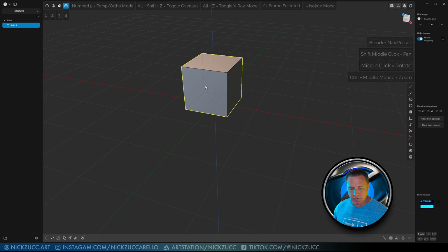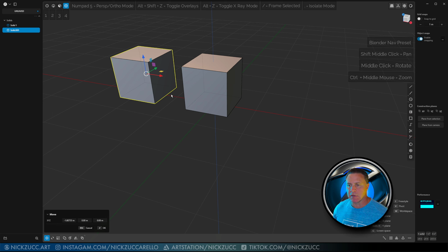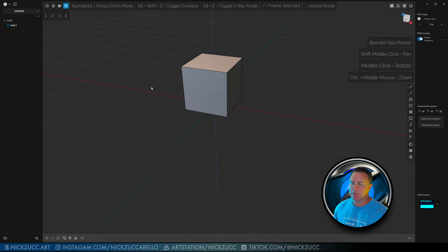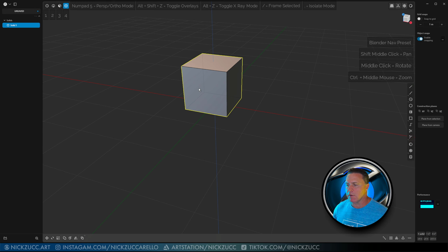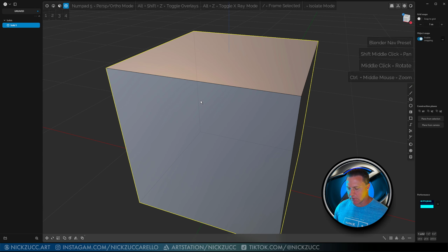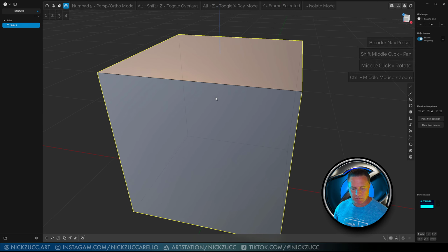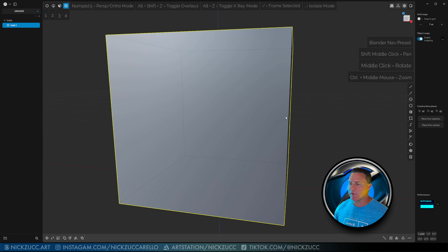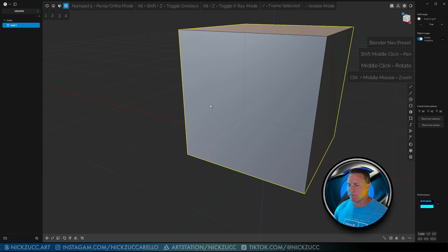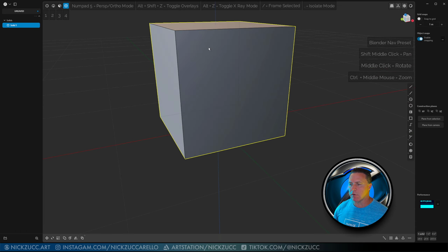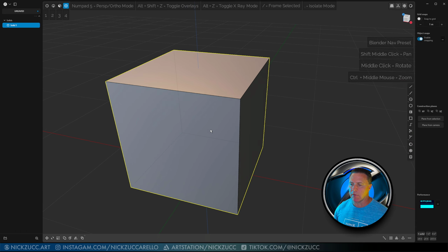So I'm just going to go ahead and select that and tap delete on that. One thing I should note with this is if I hit Shift D to duplicate, and then when I move over, Plasticity is like a lot of other CAD programs where it wants you to right click to confirm, or you need to hit this OK to finish out the operation for that. So I'm going to go ahead and click this and delete that and get rid of that. Okay, so again, if I tap the slash key, that's going to frame in on this particular thing that we have here. And then if I want to rotate about a certain point, I can put my cursor at that location, and it will try to rotate around that area.